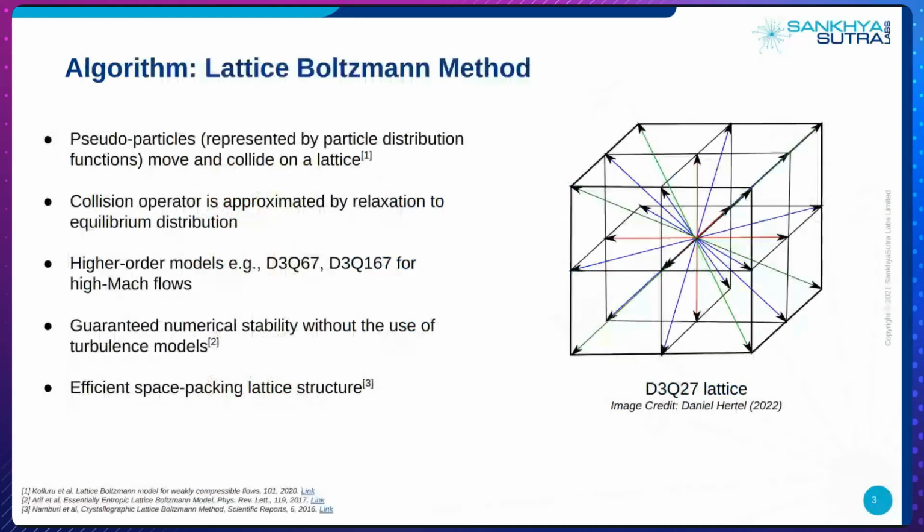So SankhyaSutra Taral is essentially a Lattice-Boltzmann method solver. It is different from conventional CFD solvers in the sense that conventional CFD solvers aim to discretize the governing equations of fluid flow, which are the Navier-Stokes equations, and then introduce some approximations to arrive at the desired solution according to the regime that you're simulating.